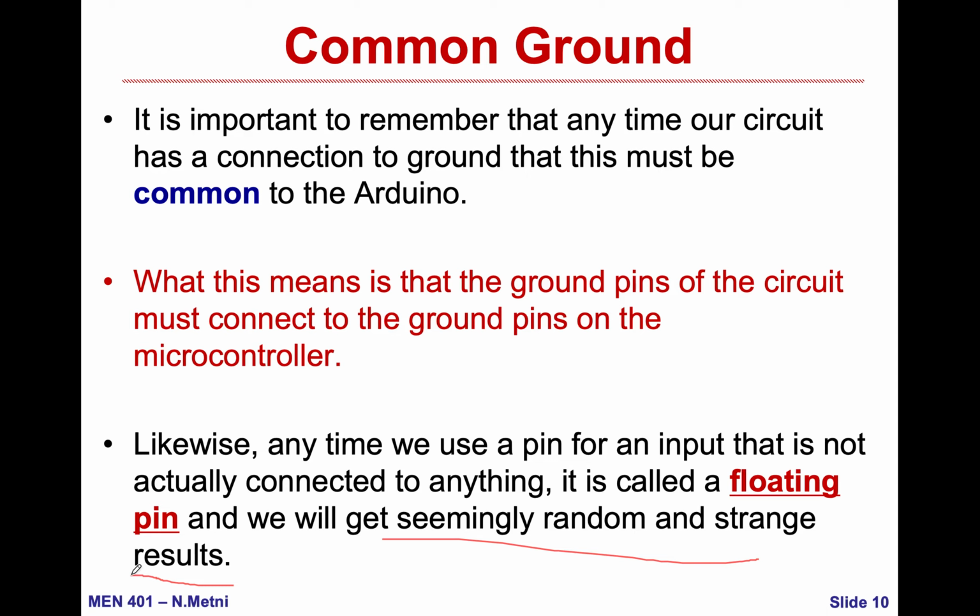So, if these pins are output, it's not important for us. However, if this pin is considered an input, I should not leave it floating, because maybe any noise will give a high on this pin, but I don't want this pin to be connected, and this will affect my program a lot. So pay attention. If an input is not used, design your circuit in a way that the pin is not floating, especially if it is an input pin.